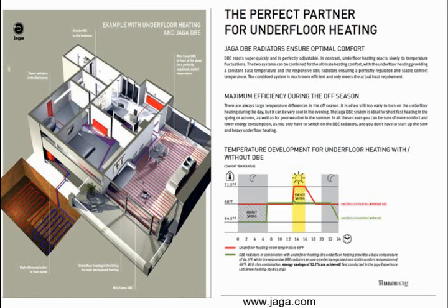Typically a concrete slab, that would be an excellent application. Those can run down at those temperatures that we're talking about, below 120 degrees. What we're finding is radiant slabs aren't always the ideal application for heating a home. If you're in a climate like I am here in Missouri where we have a shoulder season, we don't want to rev up our slabs quite yet because it's just a little chilly in the morning, but it gets warm during the day. We might want to look at putting some maybe backup system in there, maybe some little panel radiators or fin tube emitters or something like that.